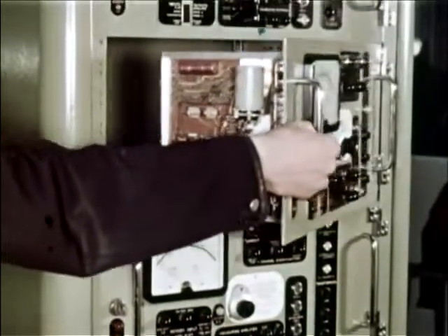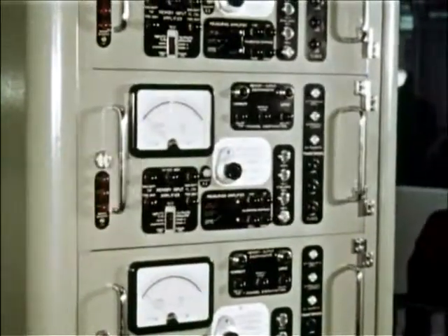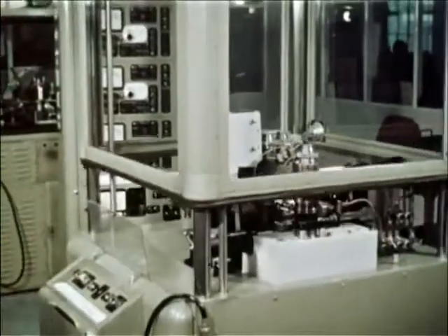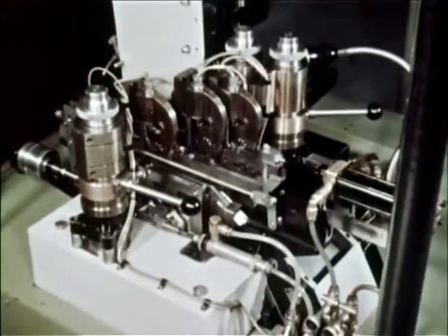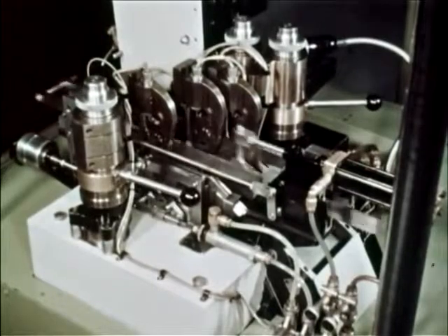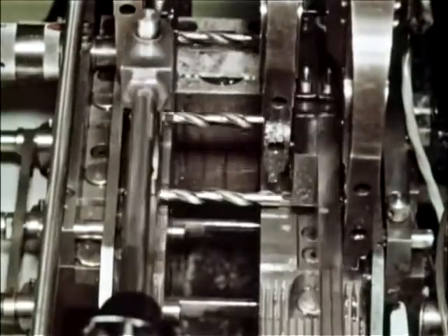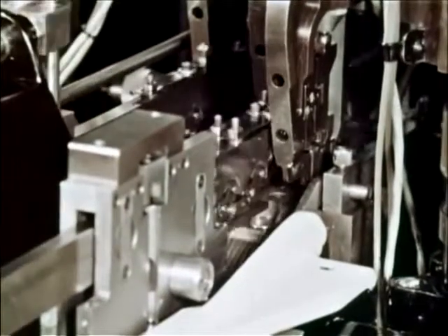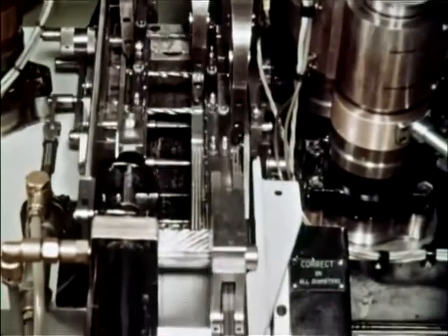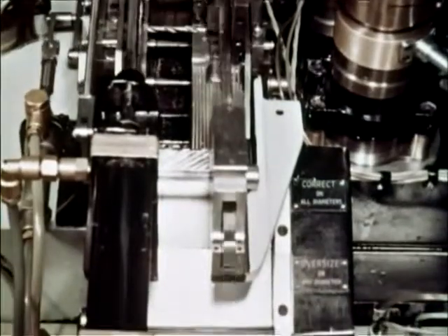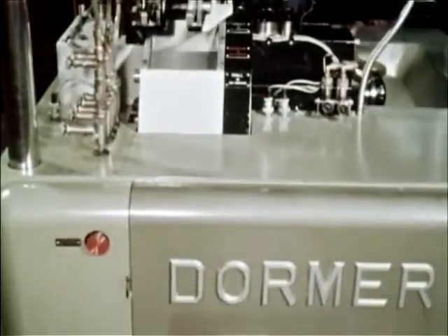British and international standards lay down strict specifications for the dimensions of each drill. Dormer have now perfected a drill gauging machine which measures drills electronically at 3 positions: the point, the run out of the flutes, and the end of the shank. Each measurement is taken separately, and the machine remembers each one, correlates them for size and back taper, then determines whether the drill is correct or not. This machine is capable of working to an accuracy of 100,000th part of an inch and inspects 3,600 drills an hour.